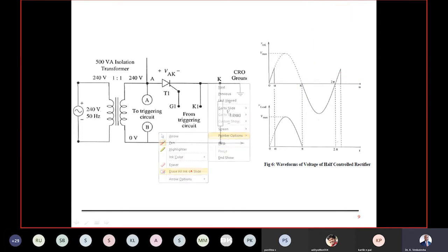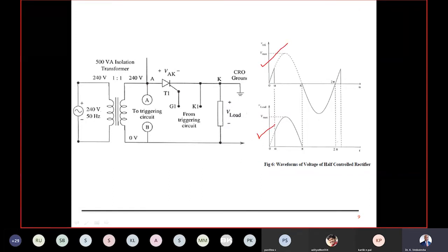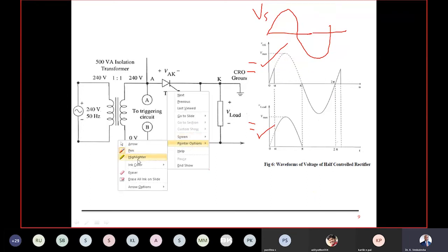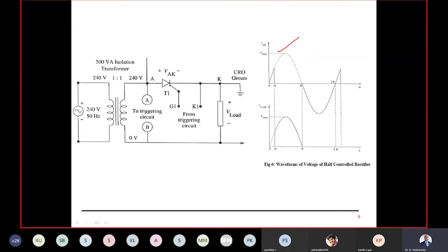That is the way. It's simple to say that if I add my voltage drop across the switch and voltage drop across the load, I get back my sine wave, because supply voltage is equal to switch voltage plus load voltage, even instantaneously. At any instant, my supply voltage is equal to the drop across my switch plus the drop across my load. So while drawing waveforms, the very simple idea is to add your switch voltage and load voltage, and I should get back my sine wave.